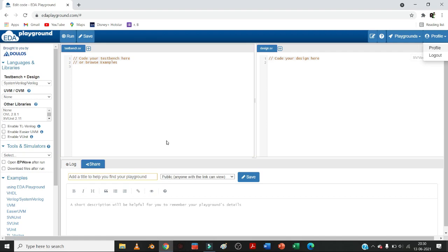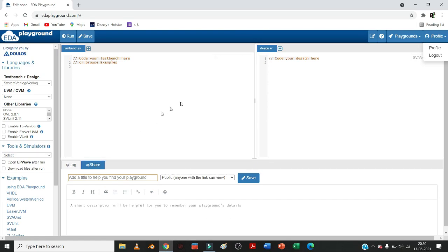Now by using these two windows, we can type our program. We can extend the windows as per our convenience. Both the windows are used for typing our requirement. Here on the right side we type the design, but the sequence of simulation will be such that the design part will be simulated first, and after that the test bench will be simulated. If we want to write some program for displaying something, we can give some module, say module test.